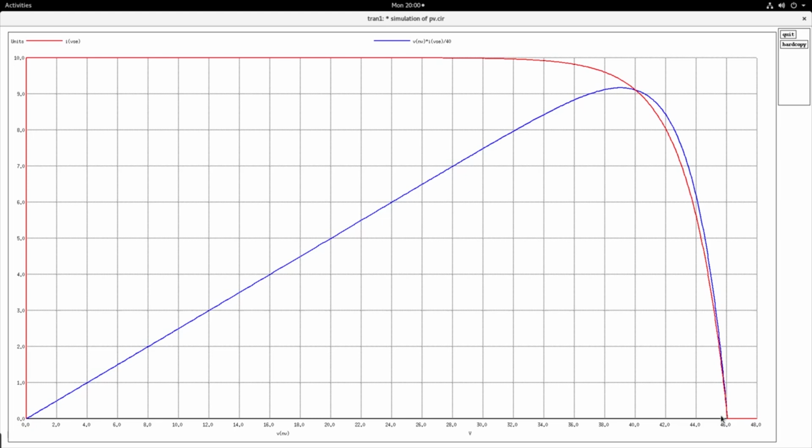This is very elegant. You don't have to do anything. Whichever be the experiment that you want to simulate, you just have to give the ISC, the short circuit current value or the insolation value, and the voltage scaling factor, and you are done. You have a PV source. We will use this PV source to simulate our MPPT tracking with DC-DC converters. So before we put in the MPPT algorithms, we need to first see if our PV source, when interfaced with a DC-DC converter, works well.